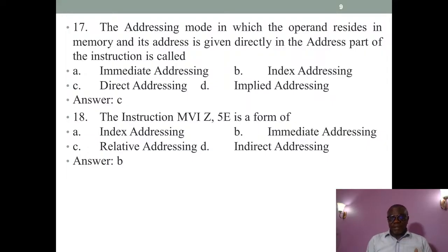We said in our previous lecture that if you have a number in hexadecimal, it is easy to get the binary equivalent. For instance, E is 1110 in binary, and 5 is 101. So you now move 0101 1110. That is the bit you will move to the register Z.